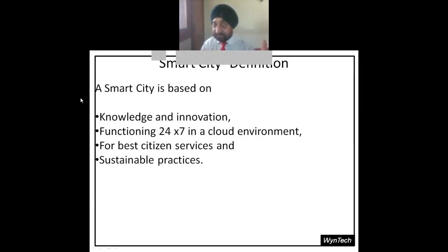And what is the vulnerability? That in the next rainy season or next storm, that joint may disconnect again and may give the problem again. But in a smart city, we have the information on when the wire was repaired last. If the wire was repaired 5 or 6 times in a month, or 6 times in 2 months, then it is better to replace it.